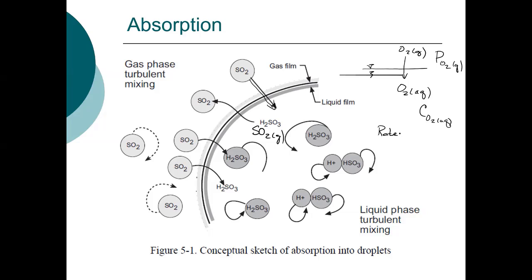Think about it in terms of the Red Cedar and oxygen transfer. So the rate of transfer is a function of what? What factors affect the rate of transfer? Or are there places along the Red Cedar where you think the rate of mass transfer is going to be the greatest? Where would that be? Think about the Red Cedar as it flows through campus. Where would the rate of transfer be the greatest? Okay, so here. It's at the weir behind Wells Hall where the flow is turbulent.